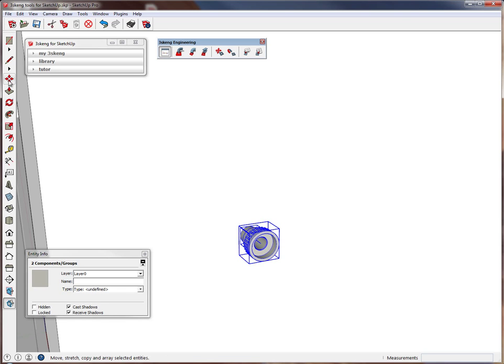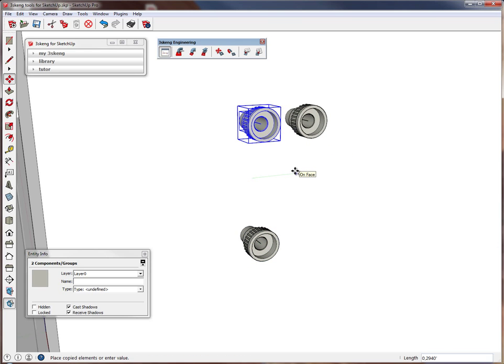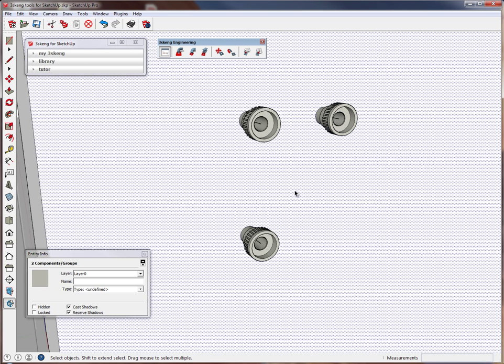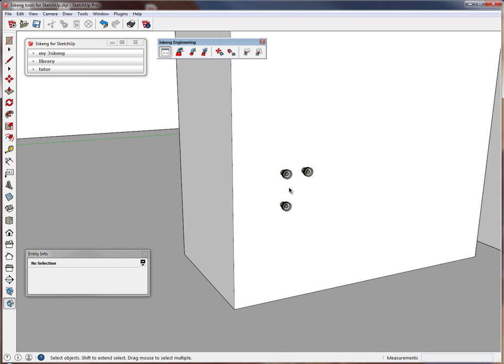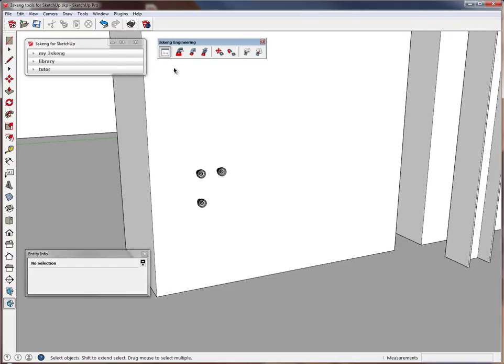We will copy the straight piece and the union to be our future cooling water supply and return. Now we can exit the component. In the detail mode, you don't have to select the pin outside visible for components because it's already predefined that way for all detail connectors.